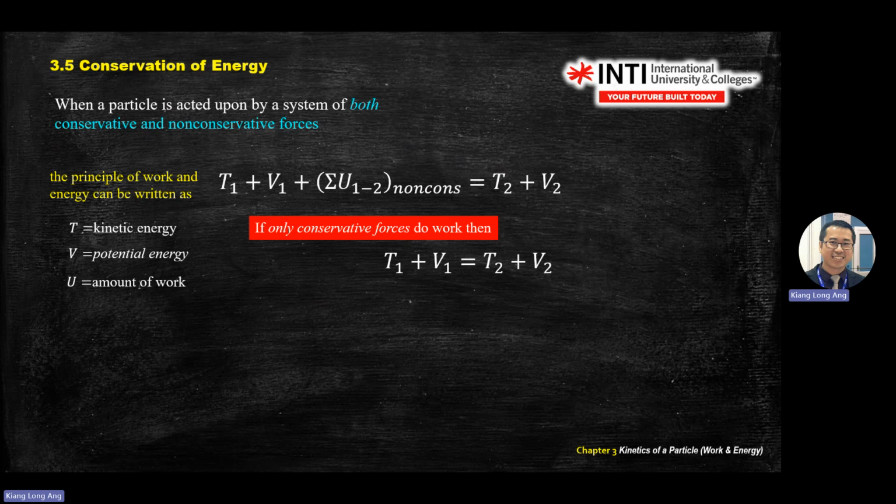As long as the particle moves with a velocity, then you surely will have kinetic energy, because half mv squared. Potential, you have two things. For potential, you need to look at the gravitational datum and the spring. You have two things here. If you don't have a spring, then you remove the spring. Okay.